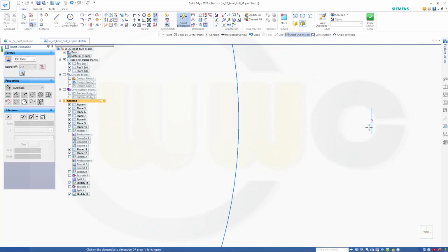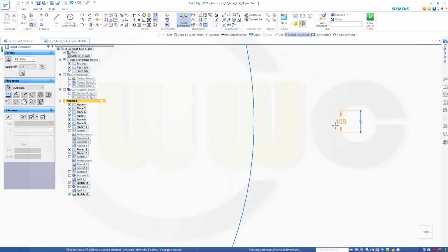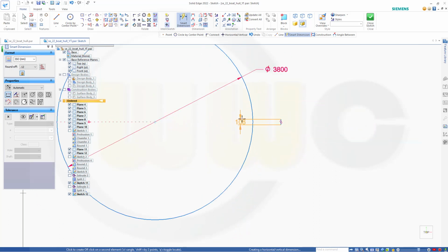So select here this one and try to go to a point, not to select the center. So I want to go to a point here. So it always will select the center, of course. So this would be 1900. In order to make it work, I go for 1900.001, which would give me that distance I need.